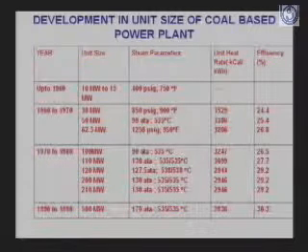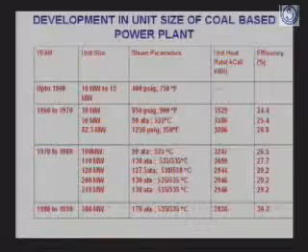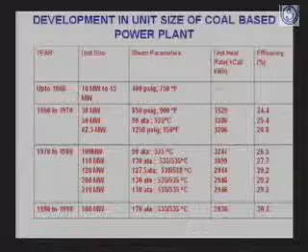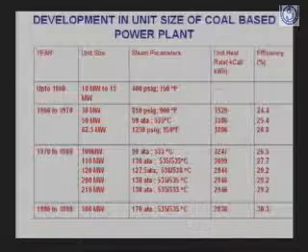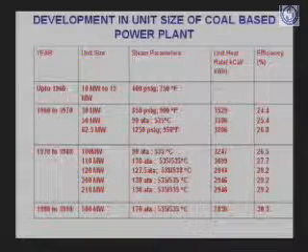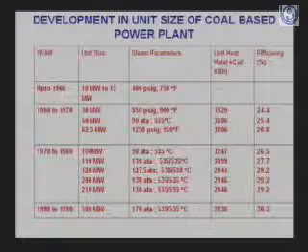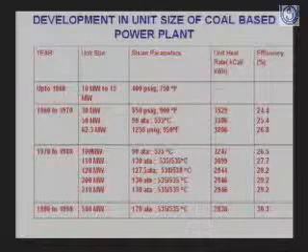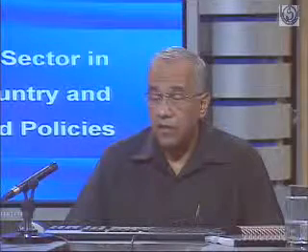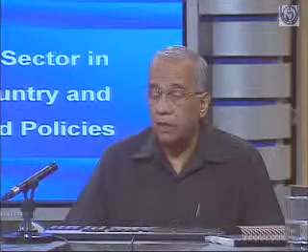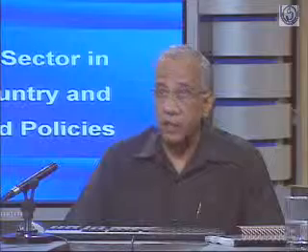Those who are not familiar with these British units can do a conversion and find out. So on the unit heat rate column, you find 3529, 3386, 3206. It means for generating 1 unit of electricity, you need to spend something like 3500 units of heat, kilocalories.